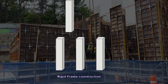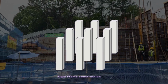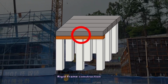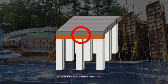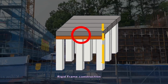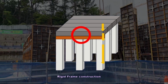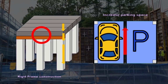A rigid frame structure refers to a structural system where horizontal members consisting of slabs and beams are connected to columns like a frame. Compared to a mushroom structure, this structure has a stronger resistance against bending and shear forces since the forces are transmitted from the slab to the column through the beam, and it also allows for fewer columns to be placed, increasing parking space efficiency.